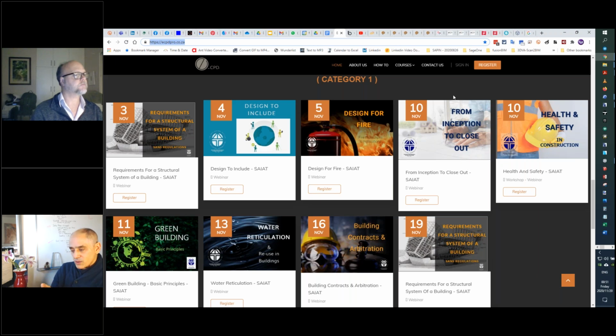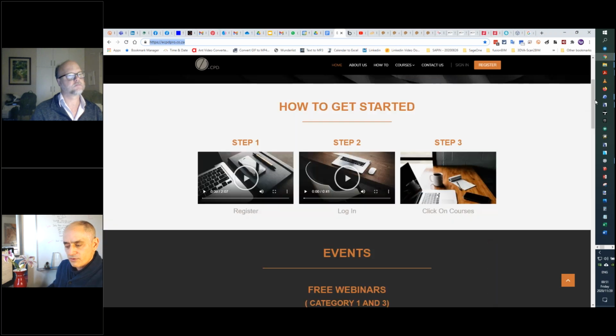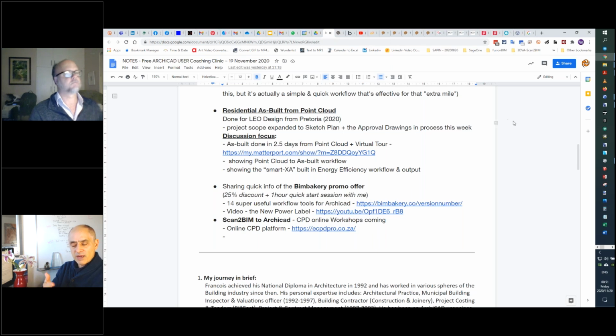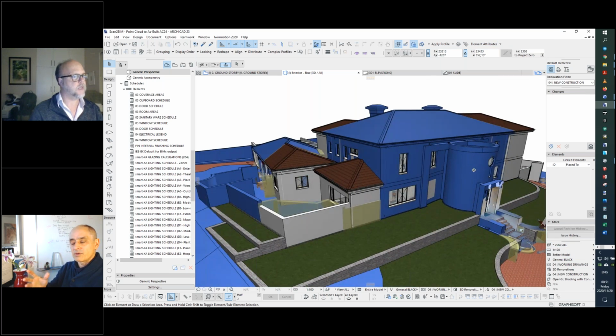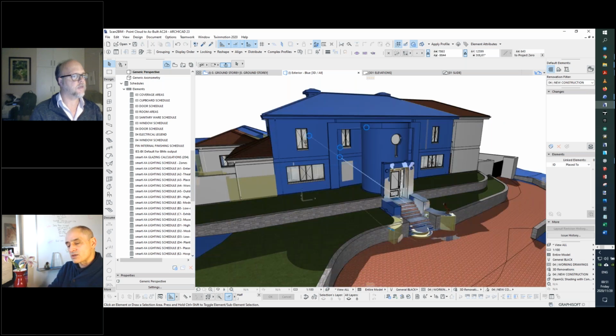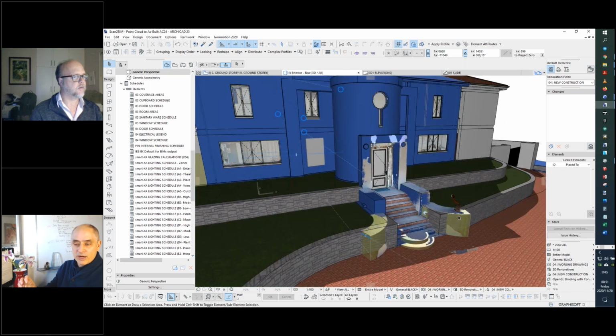Now, there are some questions specifically about this. Doug Mira says, does ArchiCAD make a morph from a point cloud? So when you bring this in, you're using that command that I think you showed that says import a point cloud, and it's looking specifically for this very long text file that has just all the points in it. And it maintains an entity, a thing that is a point cloud. So it's a unique thing in ArchiCAD, just like a beam is a unique thing compared to a wall. Now, can you convert that into a morph, or is there any reason to?